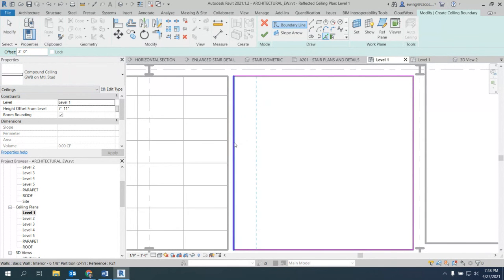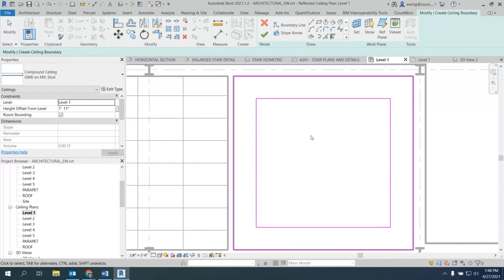So hover your cursor right over the top of that line, don't pick it. You see my hands are not on it. We'll hit the tab key once, then hit the tab key one more time, and it's going to select them all. Once it does that, we can pick that line and it should drop it in. Did it work? Yeah, it worked. Thank you. Perfect. You're welcome.